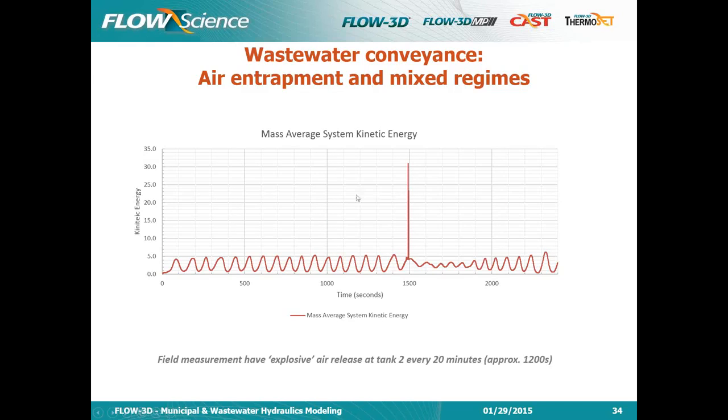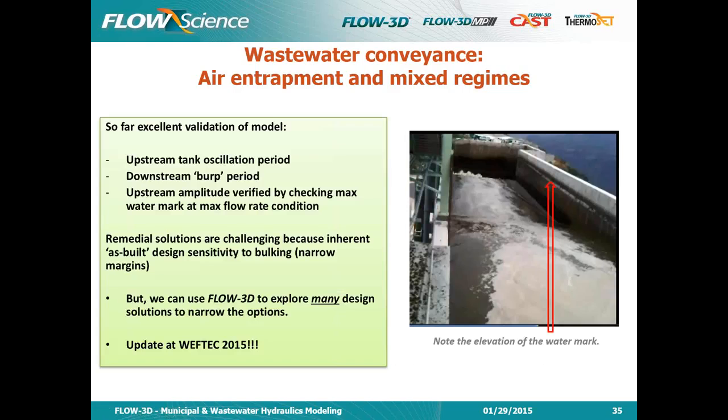And then I confess I wouldn't have run this as long had I not known about this, but lo and behold, around 1500 seconds, which is about 20 minutes or so, we did in fact observe this spike in kinetic energy in the whole system as we had this explosive release of entrapped air, which is accompanied by a large release of air in the whole system. So this is an ongoing project, and an excellent validation of the model. We have the upstream tank oscillation period, we have the downstream burp, and the amplitude of the phenomena is being correctly captured, and it's nice that we have the high elevation watermark to work with.